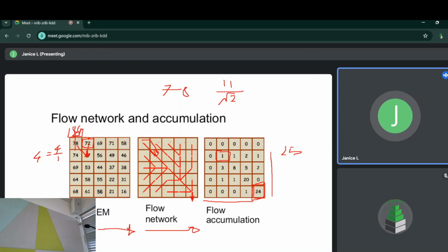What you do here is, it might be a bit more straightforward if I actually go back and forth between the slides. So first of all, you join each station to the nearby stations with straight lines. So yeah, stations, these are like weather stations. These are the stations where they measure rainfall, they measure meteorological data. That's where things are recorded, right? So a lot of times in a catchment, you're going to have multiple stations. You have station A, station B, station D, whatever. What it's asking for is join each station to nearby stations with straight lines.